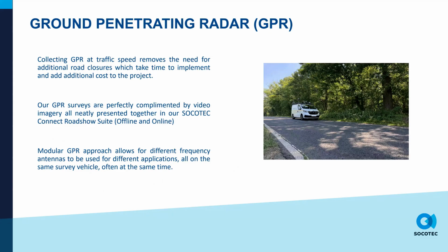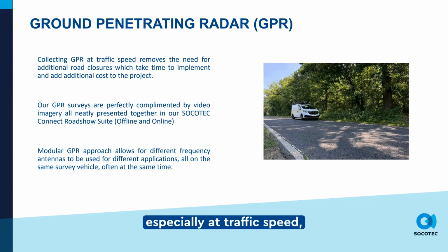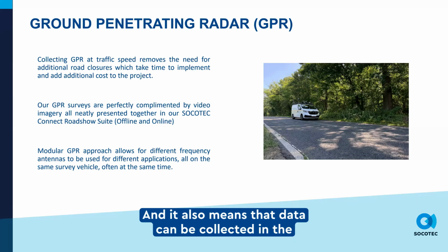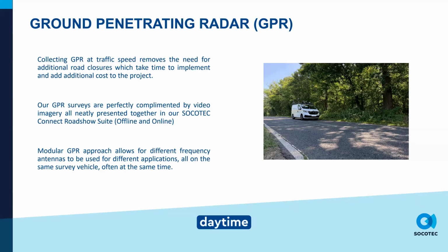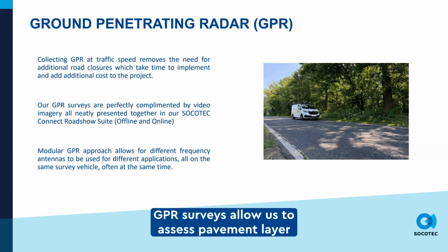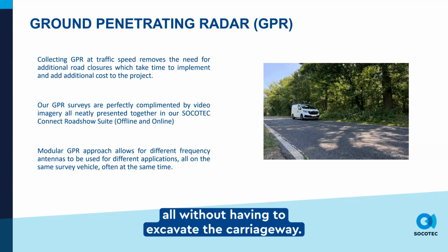There's then another area that we do here, and it is very popular on highways inspections, especially at traffic speed: our ground penetrating radar. Collecting GPR at traffic speed removes the need for road closures, and it also means that data can be collected in the daytime with accompanying video, which also helps for positioning that GPR data. GPR surveys allow us to assess pavement layer structure and subsurface condition, all without having to excavate the carriageway.